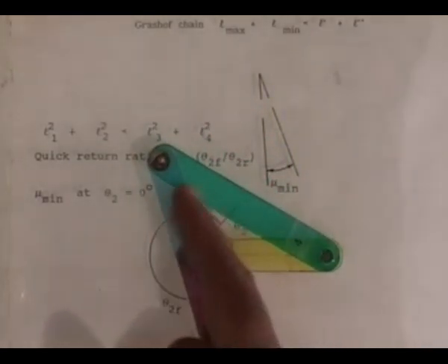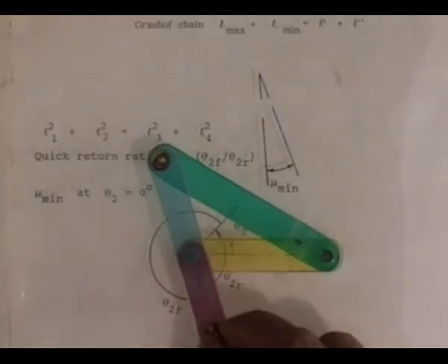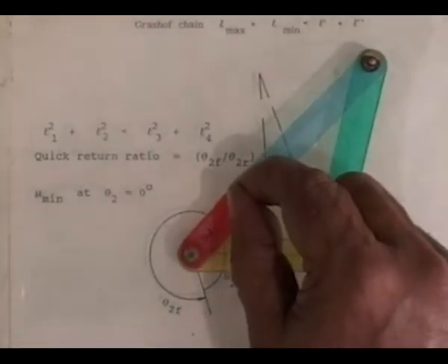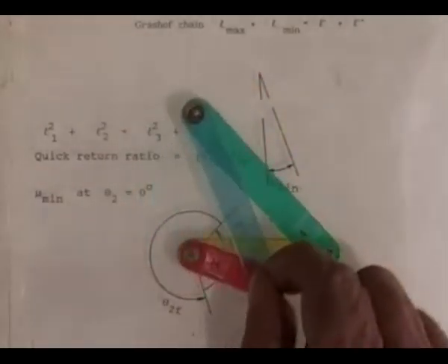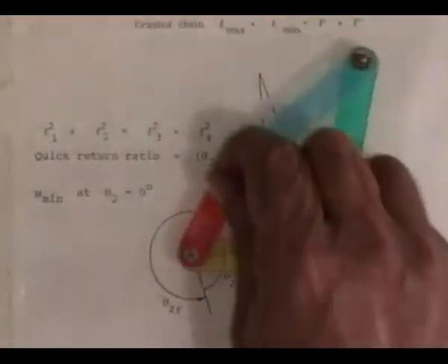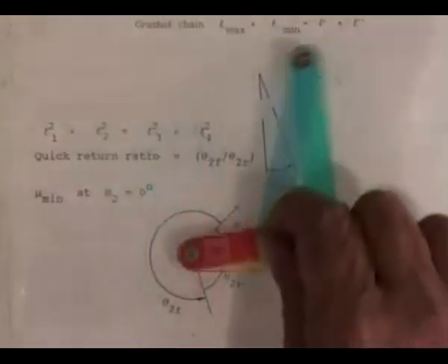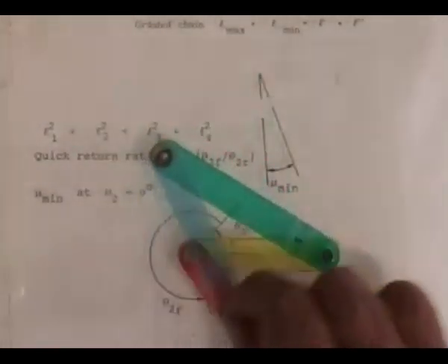So, the angle that the crank rotates is much more than pi and the angle through which it returns is much less than pi. So, if we move the crank at uniform speed, the quick return effect is much more predominant. The follower is taking much longer to come from right to left extreme and much less time to go back.